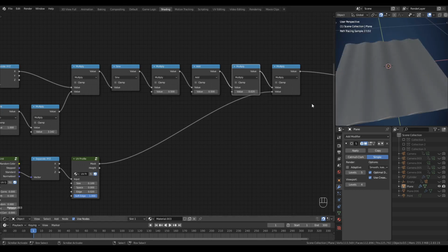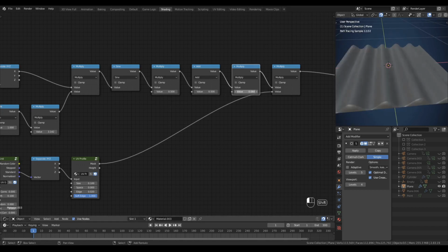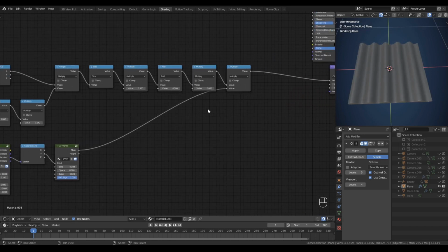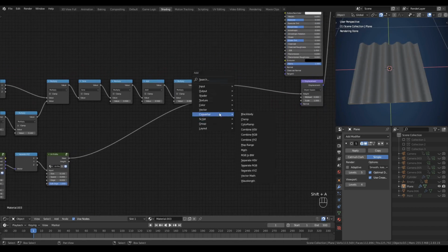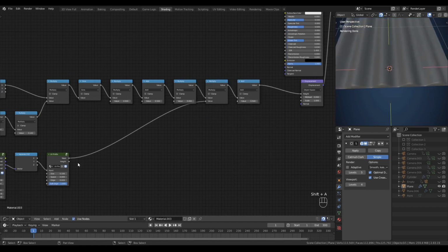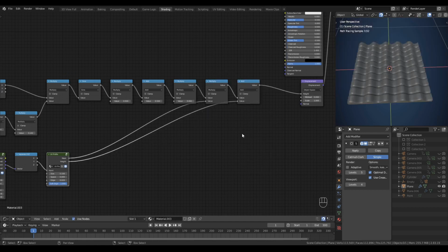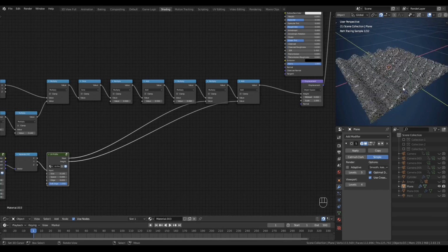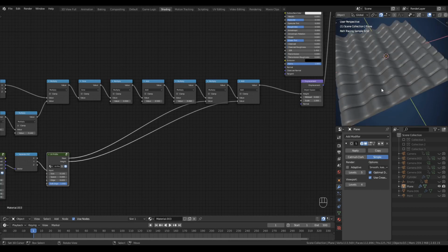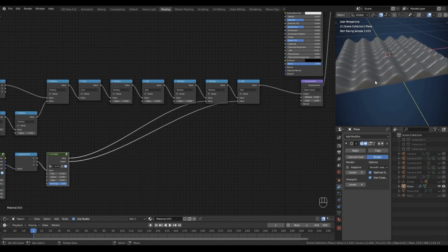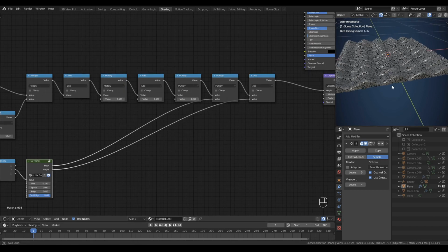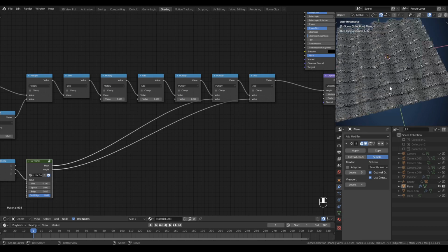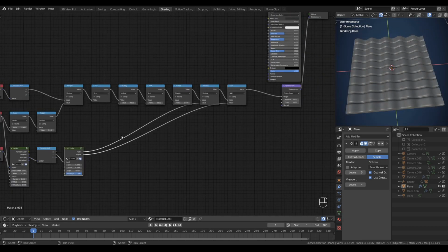Something like that should work. No, maybe a little bit more. Okay, now then, let's add the height result of the UV profile node with a math node set to add height into the bottom. And now we've got some rippling bands going on. 0.04 for the sine height. Yeah, that'll work. Looks good.